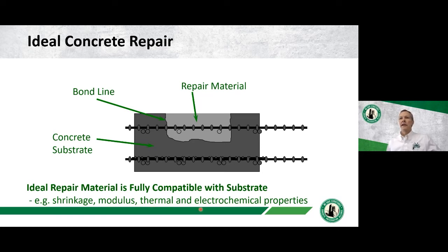than the other. And from an electrochemical point of view, or a corrosion point of view, we want to make sure that the repair and the surrounding concrete are electrochemically compatible, or to do something to address it. And this one, the electrochemical compatibility, is probably the most difficult one to achieve.